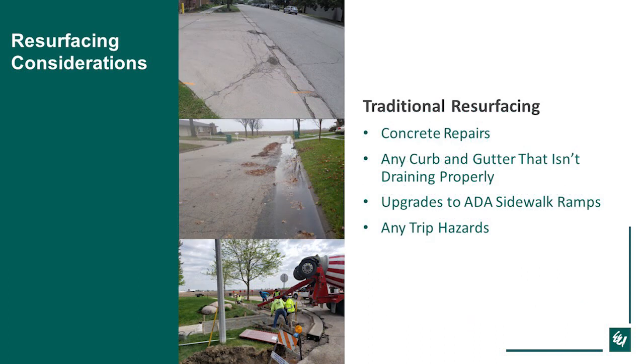So concrete repairs, each community is different and has their own standards, but at a minimum, typically you want to fix anything that's not draining, such as the picture there in the middle. That picture at the top, you'd probably want to fix that curb as well, because you're going to get a lot of moisture going through all those existing cracks, going down into your base.